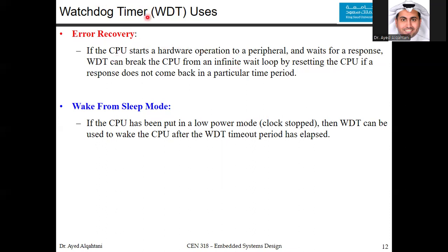The other job for the watchdog timer, as I've mentioned, is waking up the CPU from the sleep or the idle mode. If the CPU has been put in the low power mode, the clock stopped for the peripherals, partially or totally depending on the microcontroller, then the watchdog timer can be used to wake the CPU to the normal mode. That's the idea for it.